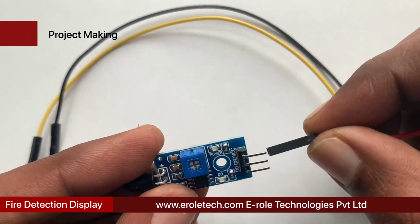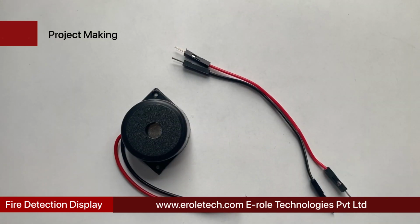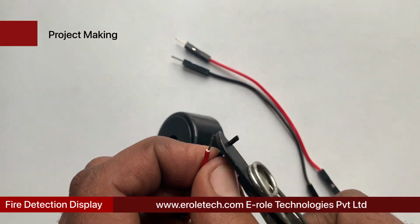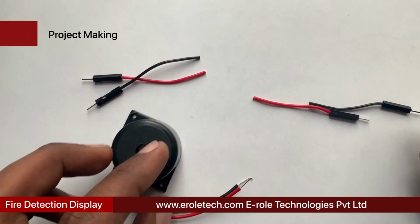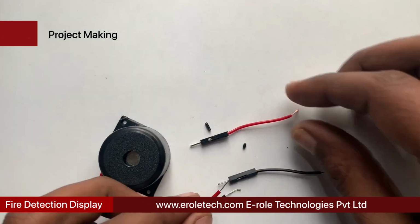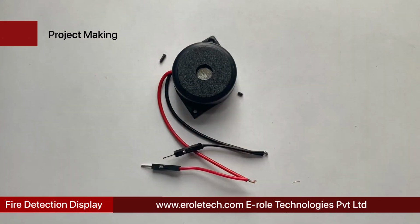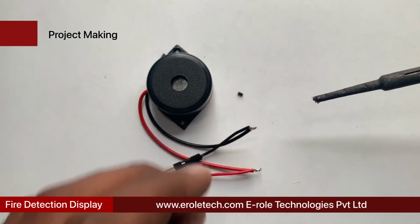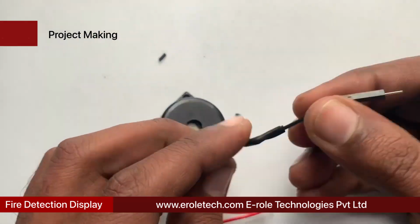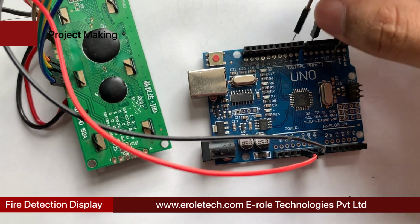Connect red, black, and yellow wires at VCC, ground, and signal pins of fire sensor respectively. Now we will take a 5-volt buzzer. We will connect a red wire with its positive terminal, and black wire with its ground terminal. Cover the joints with insulation tape to avoid any shorting between its 2 terminals. Connect the red wire with 5-volt pin, and black wire with the ground pin.